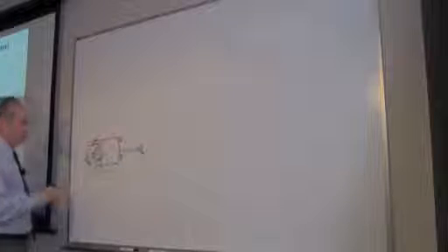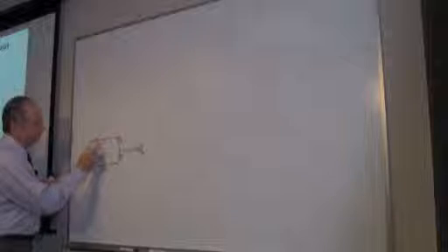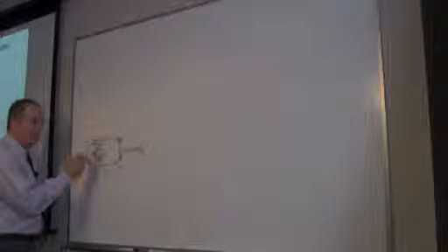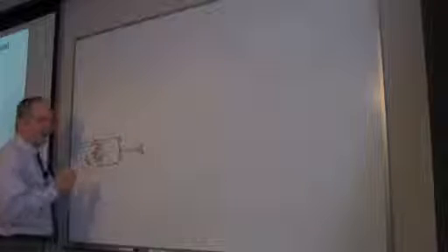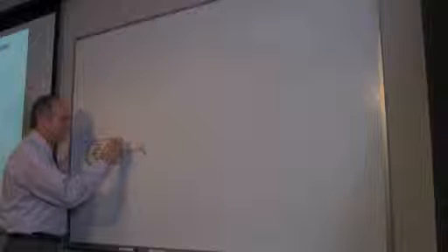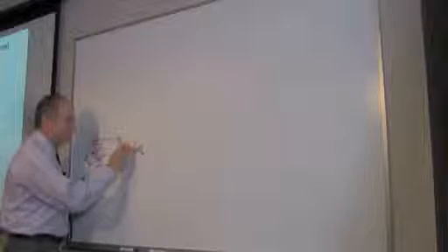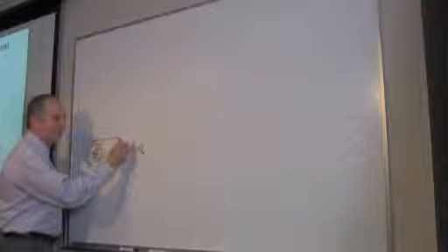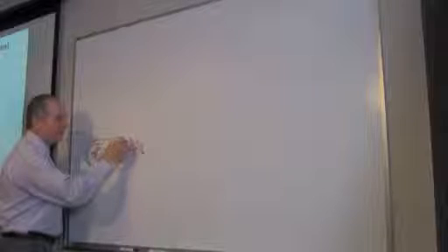And that coil of wire, if I put a DC current through that coil of wire, I'm going to have a north and a south pole. And the 2 wires kind of stick out on this end. So now I'm going to put slip rings. And another slip ring. I'm going to take one wire connected to this slip ring, the other wire connected to this slip ring. I'm going to have some brushes touching the slip ring.